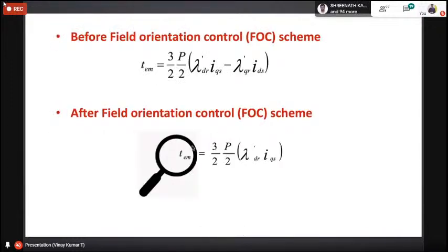So in the case of field orientation control, the first step is to extract the currents, and whatever feedback signal you are taking, you have to apply the Clarke transformation to it. Basically the torque is a seventh-order expression. Let us take an induction machine for understanding purposes. The motor is an induction machine, and the control logic is FOC. Basically the machine is a seventh-order expression. So by taking stator currents, by estimating the rotor currents, and by estimating theta r, you will get the torque expression in seventh order mathematically.